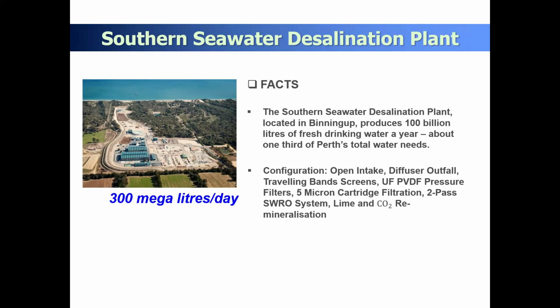That's your first task. In dual media filtration, one is sand, another is anthracite. In dual media or multimedia filtration, people use sand, anthracite, and granular media.